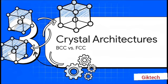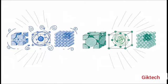Because not all of these unit cells are built the same way. Nature has a few favorite blueprints it uses to arrange atoms. And for most of the metals you're going to run into as an engineer, it really just comes down to two main designs. Over on the left, we have the body-centered cubic structure. We just call it BCC.